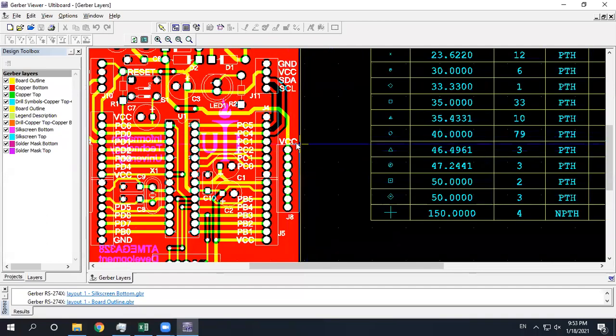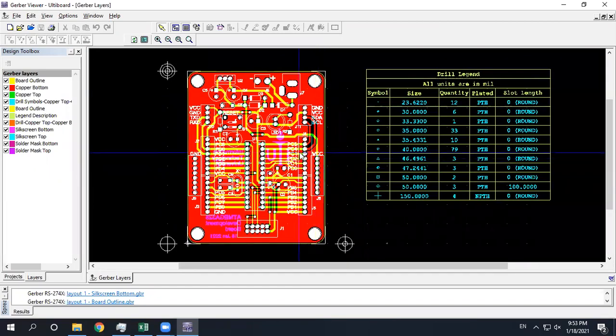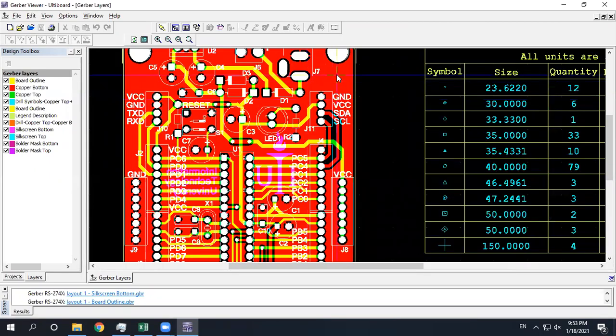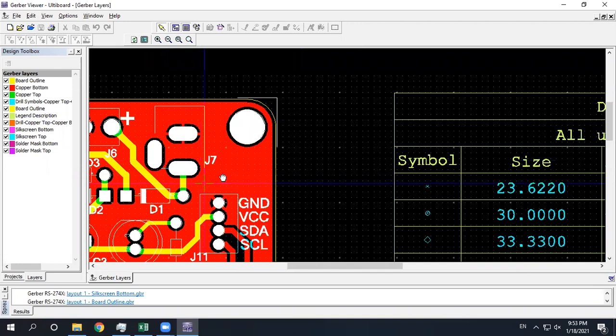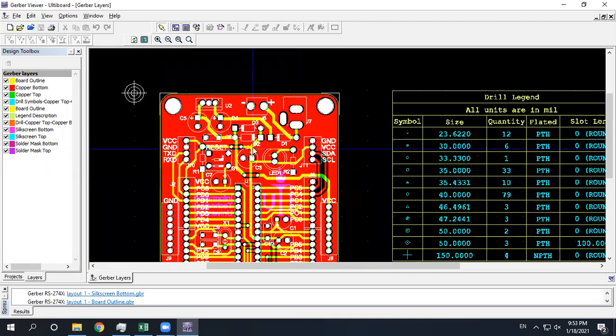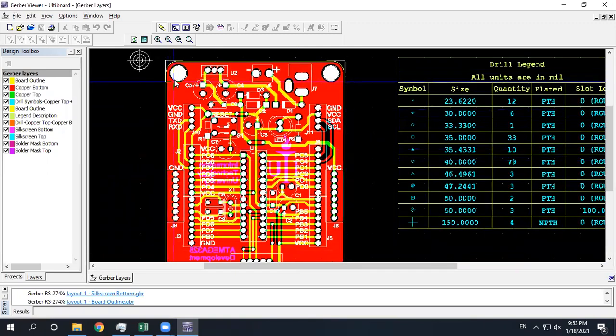You cannot change anything from here. You cannot select these and change these. These are final fabrication files. So it is important to understand that Gerber files are physical files. These define the geometry of this design. There is no information about any copper layer or any other physical property of these layers. They are just the design layers. It is just like artwork, like a picture.